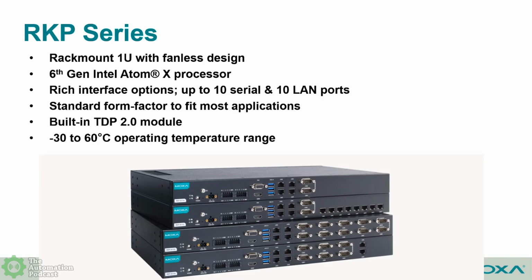So you can actually have 12 devices attached to this particular equipment, and they'll all have their own MAC addresses. They'll all be independent, so you don't need switching equipment to expand. It has 10 software selectable serial ports and 8 digital inputs and outputs. The communication interfaces are also located on the front panel, again, to enable easy access.